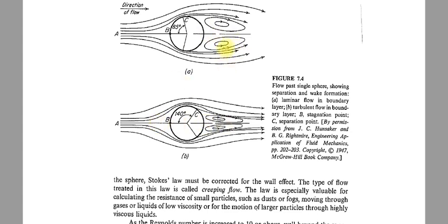This vortex will create the form drag, and the friction between the layers and the solid body will create the wall drag. Generally, if the fluid is flowing at a much higher speed, the form drag will be highly dominant over the wall drag. So if this vortex is small, that means the form drag will be reduced.